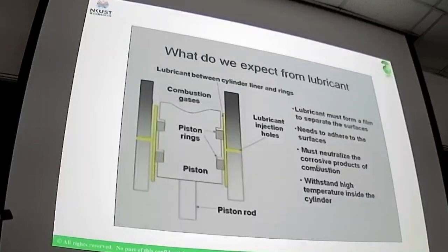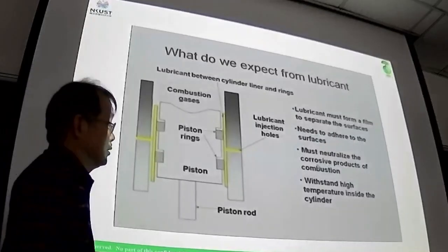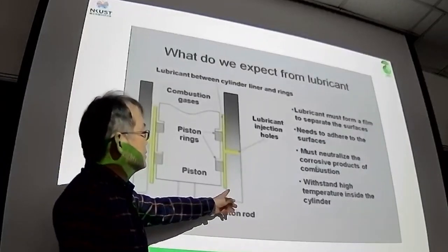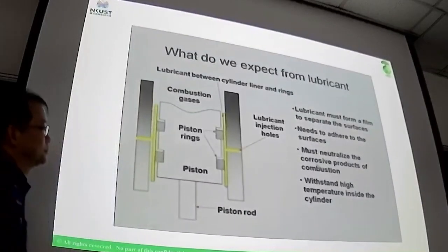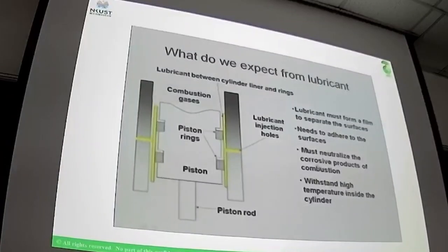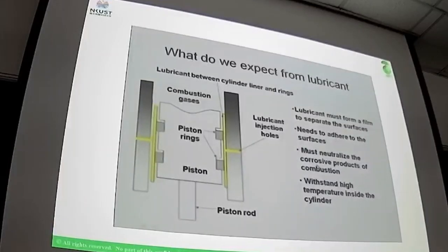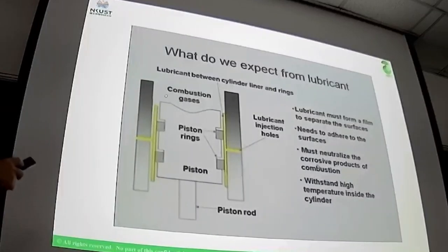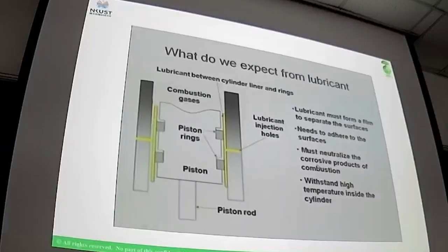So the lubricant should form a film to separate the inner surface of the cylinder and the piston ring. Also the lubricant needs to attach or adhere to the inner surface of the cylinder. And then once the oil and air get burned, you have some debris or some leftover.